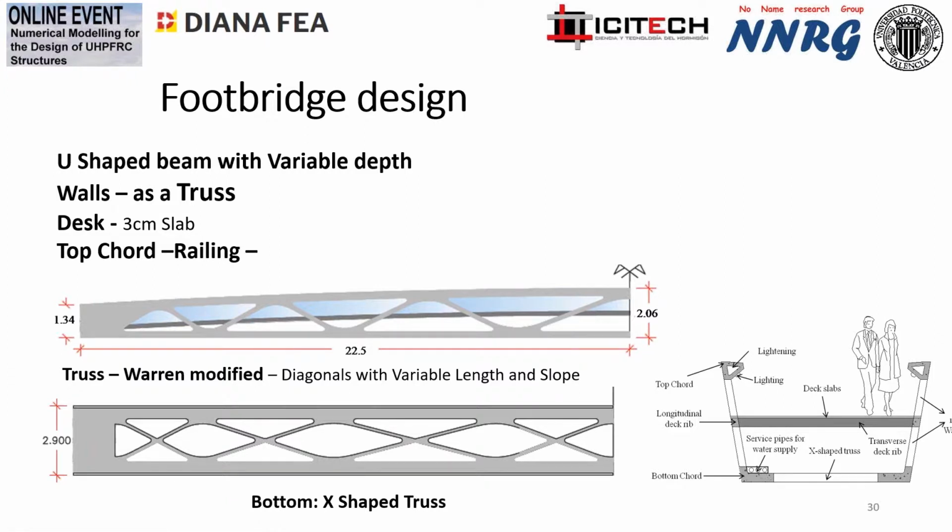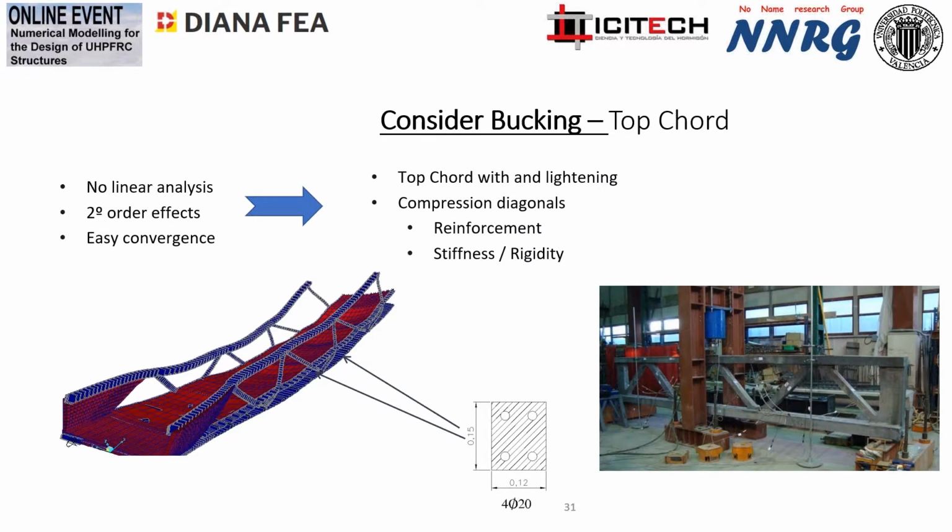The advantage is the multi-functionality of all elements. The railing is the compressive core, the top chord. Only with that, it is used to transmit all the compressions. And this part, only this part, is the tensile chord. This is the minimum place to incorporate all the pre-stressing strength.